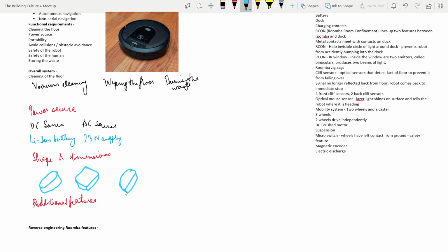You can think about how it does navigation. If it were a semicircle, it would have no problem with anything at all. The thing I think maybe with the circle, the benefit is the center of mass shifts to the back, so it can use it for staircase detection. The center of gravity is behind, and it has this infrared sensor in the front, so it detects the staircase before it falls. So that is where this advantage is coming from, this circular backside as well.